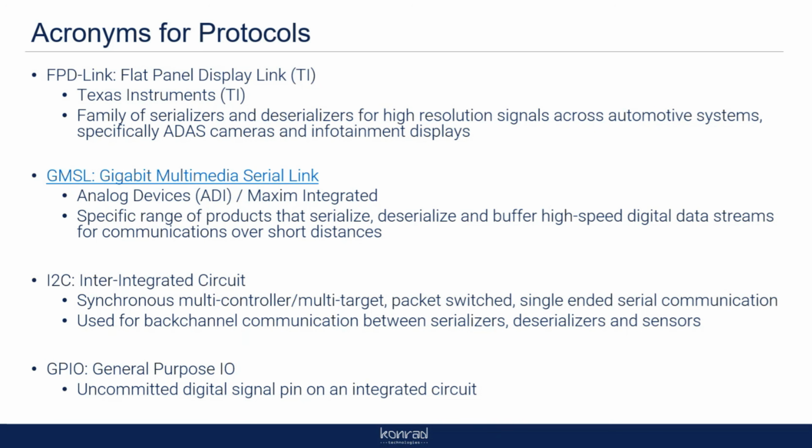I know my husband's vehicle has a newer display in the front that has the CarPlay and all that fun stuff. And it's an FPD-Link 4 display. And the cameras in the vehicle are FPD-Link 3 as well, because there's a lot of compatibility between them. And what's interesting is, with the NI equipment, we can read the FPD-Link cameras, but we can't generate FPD-Link display because we don't have the appropriate serializer to go to their chipset.